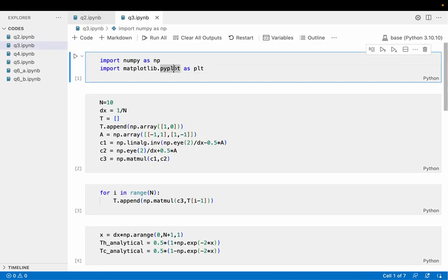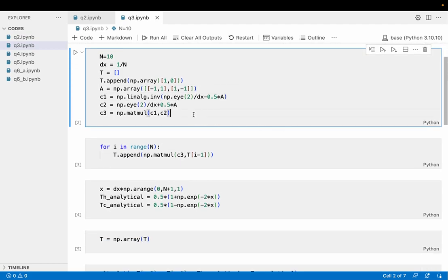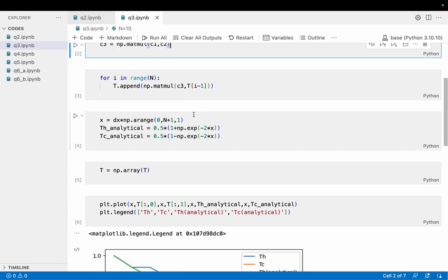So this is for the parallel flow heat exchanger. It's again straightforward. I've just taken the A matrix here, like dTdx equal to A times D, that is the governing equation we were having. Your A is given by -1, 1 and 1, -1. So I've just defined some constants here so that it will be a little easier later.